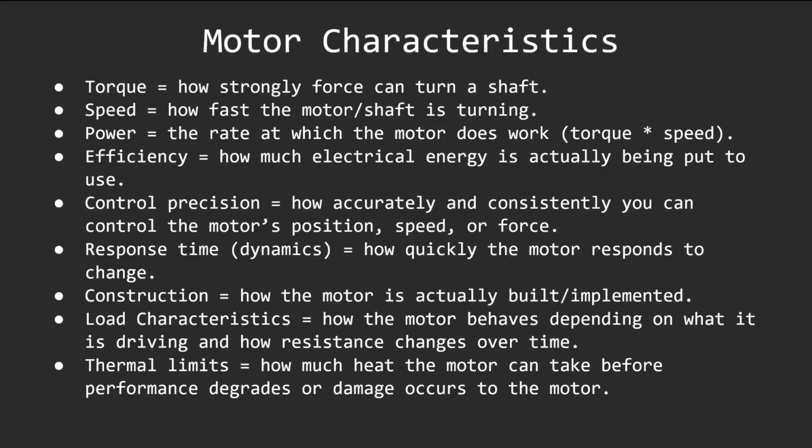And then there's the efficiency, how much of the electrical energy is actually being put to use. 100% is impossible, about 80% is good. Anything below 50% is poor. And then control precision, how accurately and consistently you can control the motor's position, speed, or force. This is very important. Then we have our response time, also known as dynamics. This is how quickly the motor responds to change.